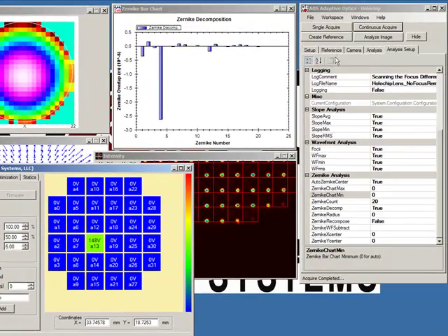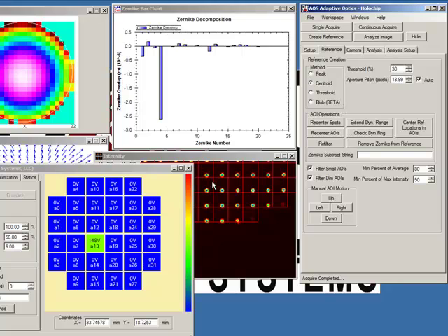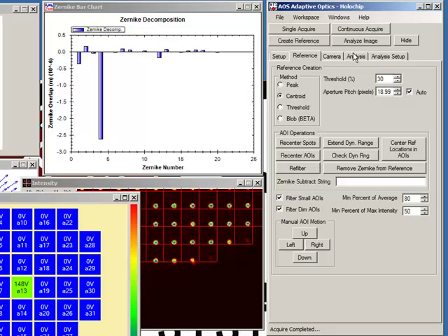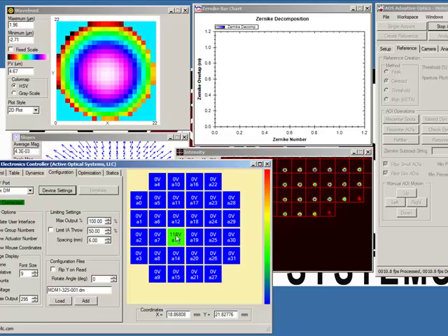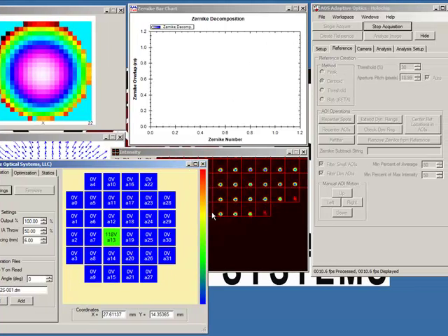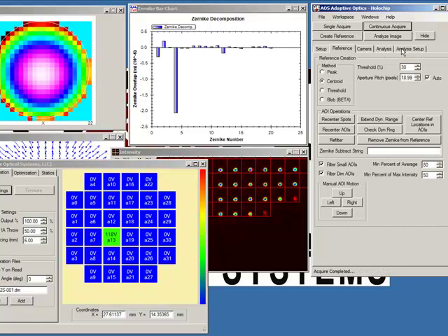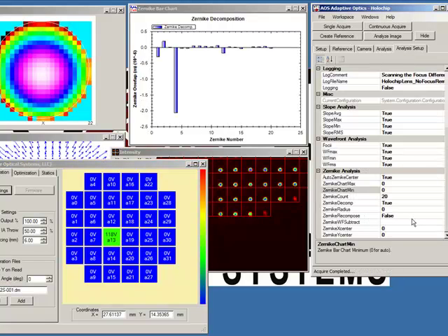Now, we can go in and make some adjustments and try to alleviate that, but for now I'm going to leave that alone and see if we can collect some data here. Specifically, what I'm interested in is, at 148 volts, how much other aberrations are existing. Just to make sure I am not hitting that dynamic range issue, I'm going to bring it back even a little bit more. We'll call it 118 volts. This looks like the spots are in the boxes. That looks pretty good.